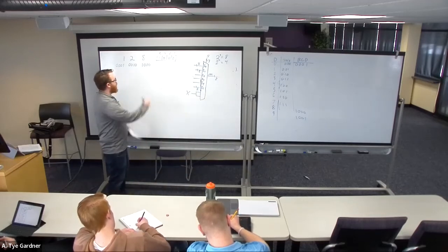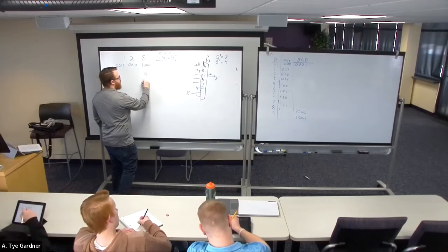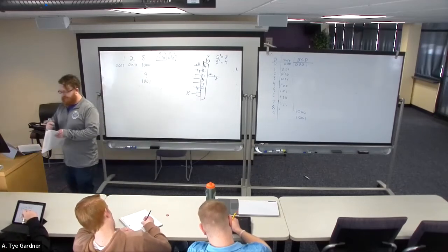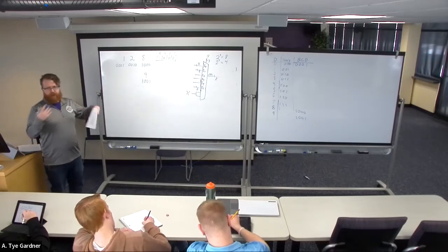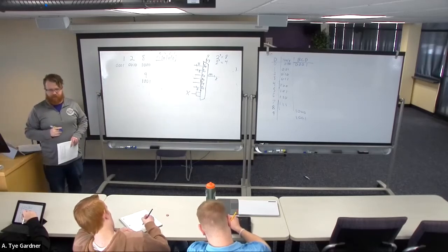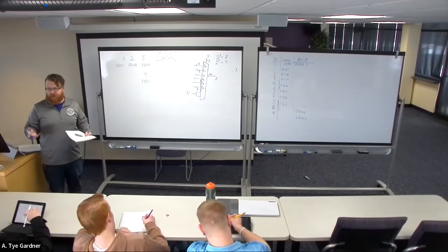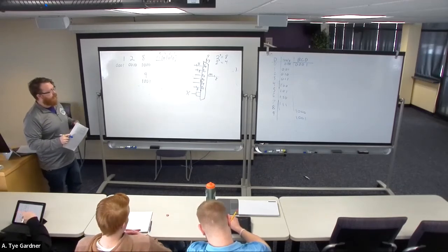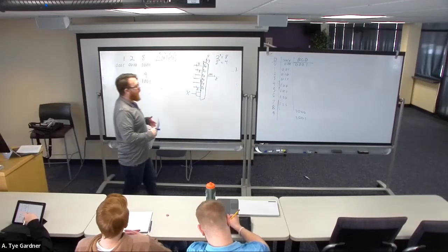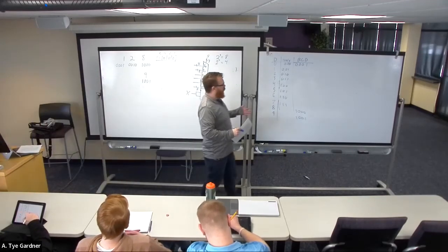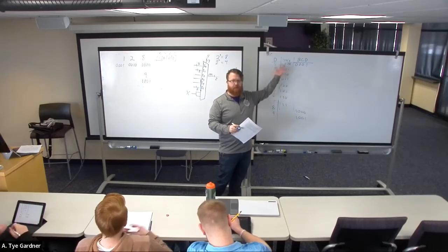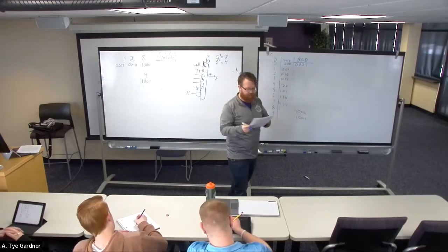That 8, 9 would be, unless I did something wrong, which I don't think I did, how we would encode binary coded decimal. It's just one way of storing numbers. It's just a different way. And we could then go ahead and start designing converters, right? It's just a truth table. I could have some inputs, take some output, and design digital logic that transforms it.